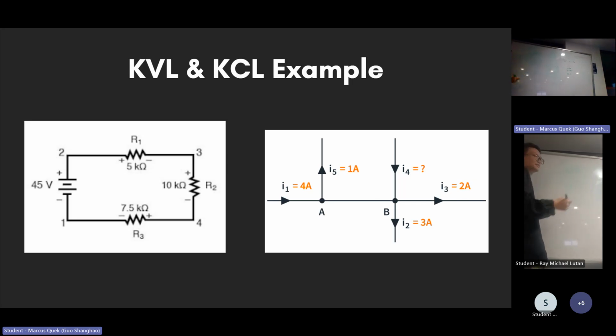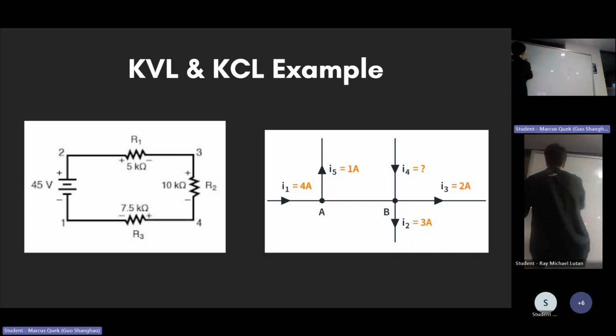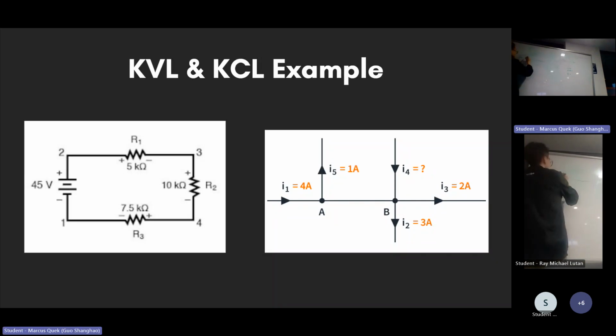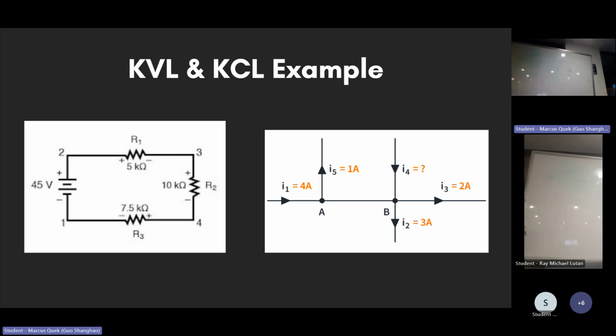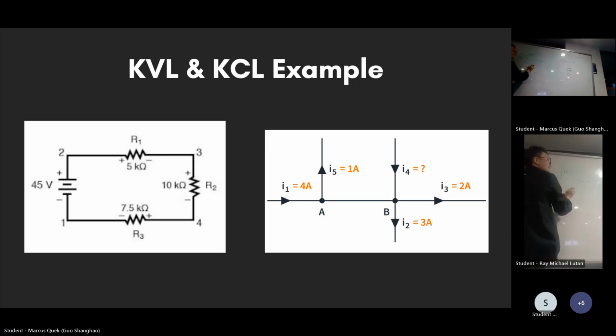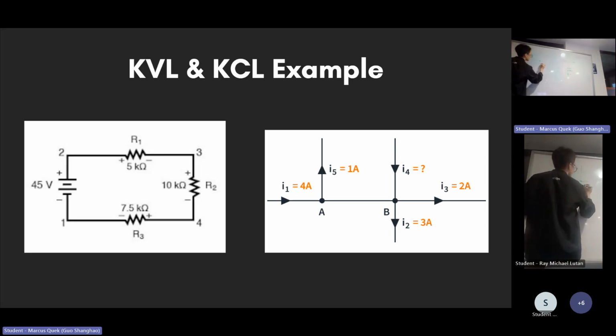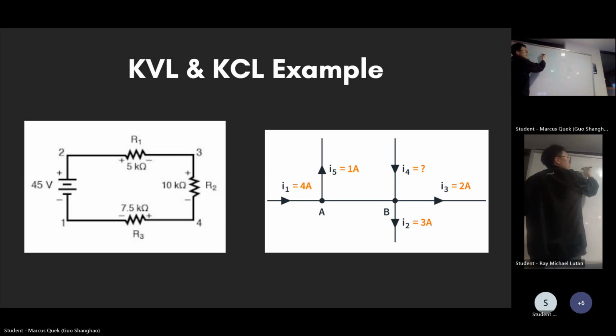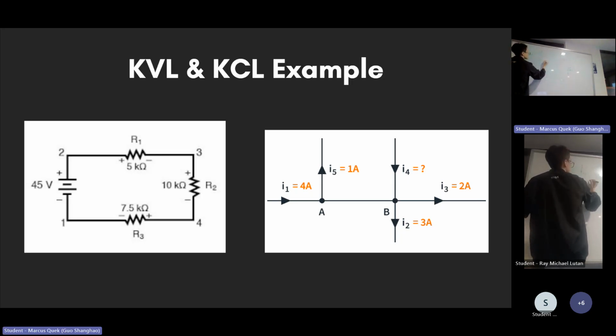For the bike, let's look at the bike circuit first. This uses control current. So current in, let me just draw this. I1 is at the bottom there, 4 amps coming out here, 1 amp here, then 3 amps here, and we want to find I4. 2 amps here.